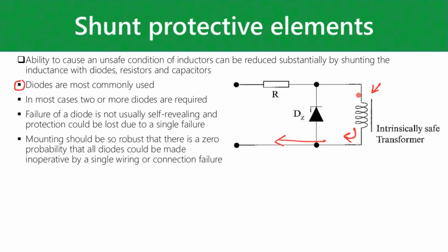And you're also going to have the voltage across your inductor change as well. Now, if you put a diode in parallel to your inductor, that's going to provide a current path for the flyback current to go back to the inductor. So essentially the inductor is going to dissipate that energy through the diode and itself. Remember, this thing has a little bit of parasitic resistance to it as well. So instead of that going back to your circuit and potentially destroying a transistor or causing a spark somewhere, it is contained at the coil itself.